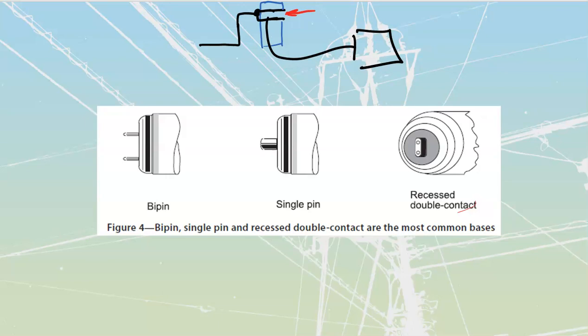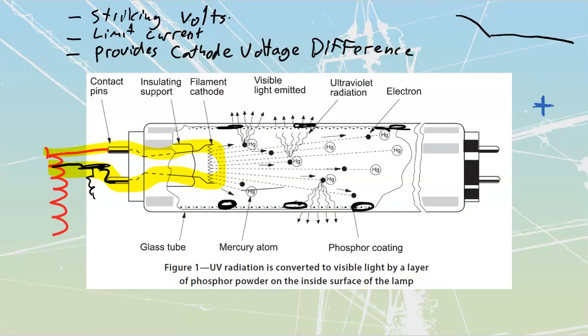We do have a couple of other types of specialized fluorescent lamps. The other ones that they're going to talk about are germicidal or black light ones. Black light ones have a weak amount of phosphor. It is still a phosphor coating, but it changes all of my UV radiation. It only slightly shifts it, so it's just barely within our visible range. That's why they get that purplish sort of glow. We can take that little bit of glow, place anything neon underneath it, and it tends to glow. They're not generally used for lighting, outside of clubs or places like that.